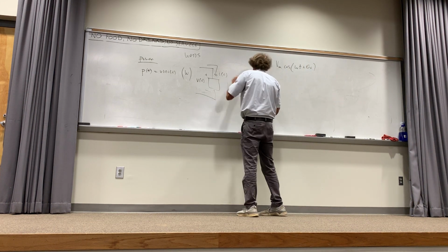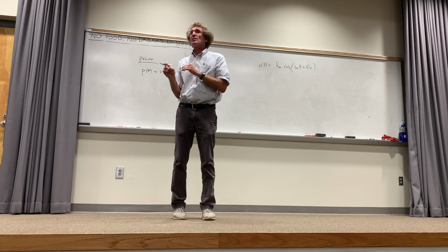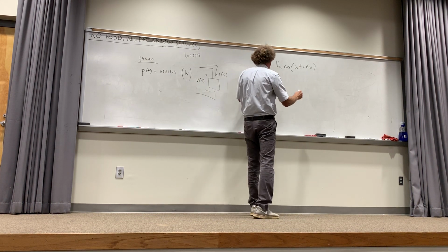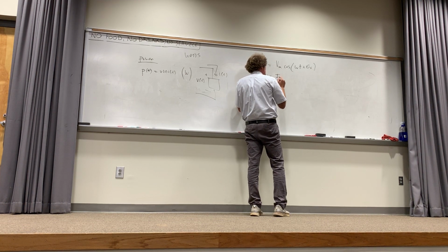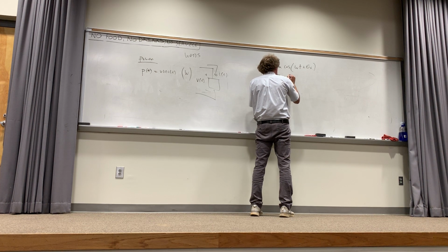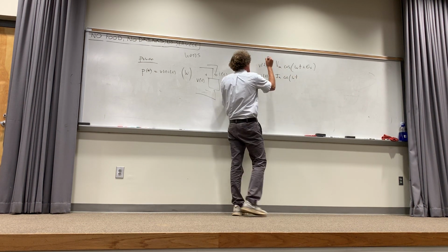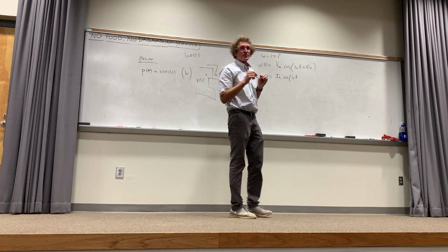The current, if that is the voltage driving the current, will have the same exact frequency. It'll have the same cosine form. So i of t will have I_m, that's a magnitude, times cosine of omega t, same exact omega. And omega, I hope we all know this, is just 2 pi f, where f is the steady state frequency.